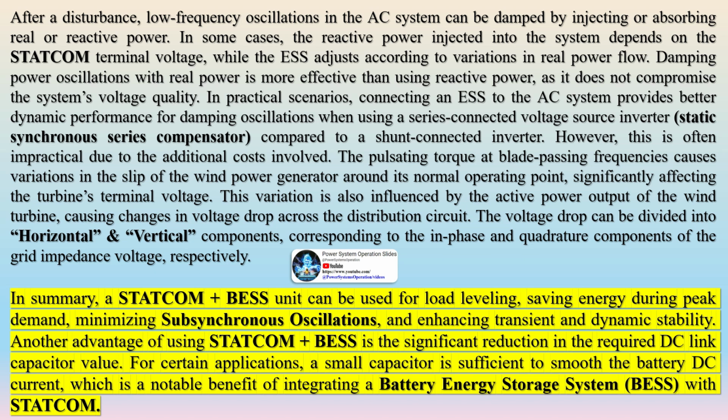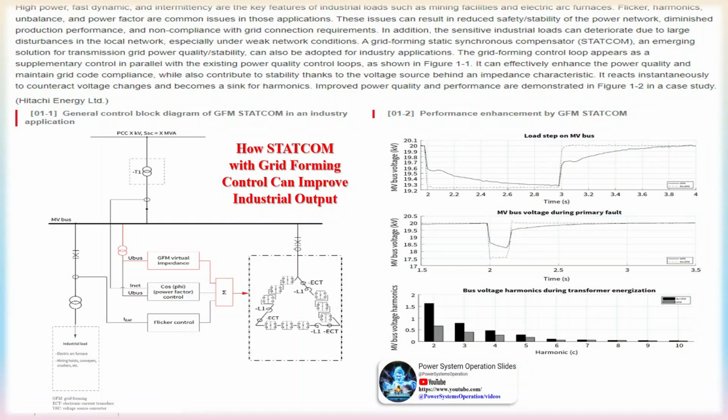To establish a realistic cost estimate, the following steps should be considered. Identify the system issues to be addressed. Study preliminary system characteristics. Define basic requirements for energy storage, power, voltage, and current. Determine the utility's financial benefits from system integration to assess the return on investment. Model system performance in response to demands to evaluate the effectiveness of the BESS. Optimize integrated system specifications and determine the overall system cost. Study and compare the performance and costs of various energy storage systems.